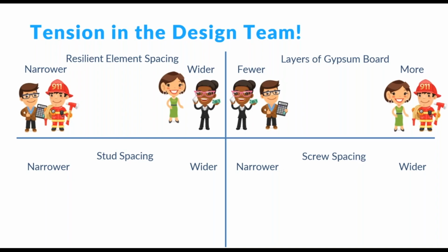And in acoustics, we want more gypsum board too. Mass resists that movement. Sound moves from one side of a wall to the other. Sound is air pressure waves, and so it's those pressure waves making the wall move, and then that makes the air on the other side move. The heavier that wall is, the more energy it takes to move it. So more mass, more sound resistance.